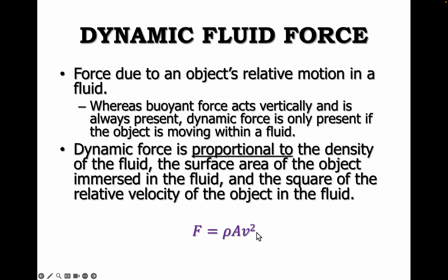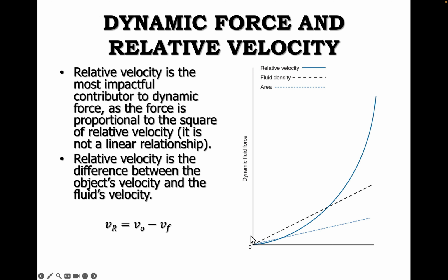Because velocity is squared, the relative velocity is going to have the biggest impact on changing this dynamic force. What relative velocity is specifically is the difference between the object's velocity and the fluid's velocity.